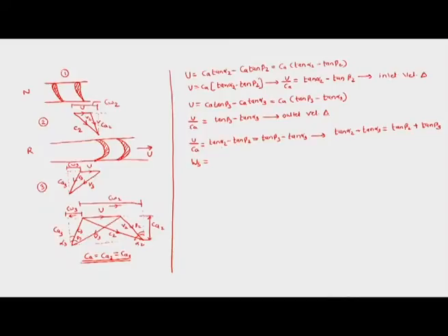That is the formula we obtained from the Euler turbine pump expression. So W is equal to m dot into u into Cw2 minus Cw3. This is the stage work for the turbine, but here we can see that Cw2 and Cw3 are in opposite directions. So we have m dot into u into Cw2 plus Cw3. So this is in general.